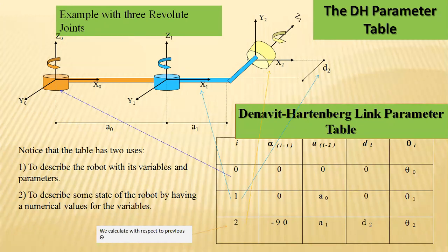In the spherical coordinate system, there is one revolute joint and two prismatic joints, hence it is not suitable. The third one is the polar coordinate system, with two revolute or rotary joints and one prismatic, which is also not suitable. Finally, we have the articulated coordinate system, or jointed-arm coordinate system, which has three R joints, that is rotary or revolute, revolute, revolute.